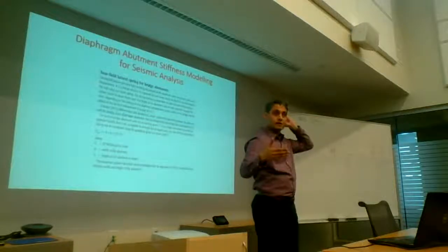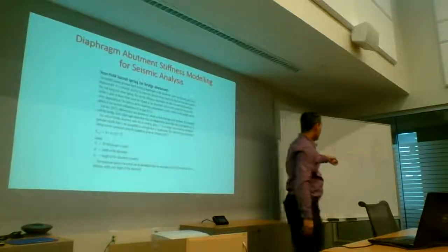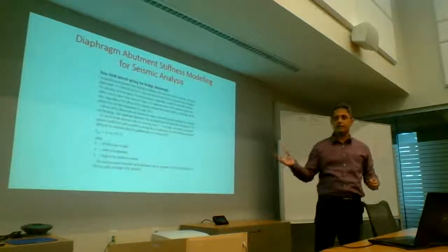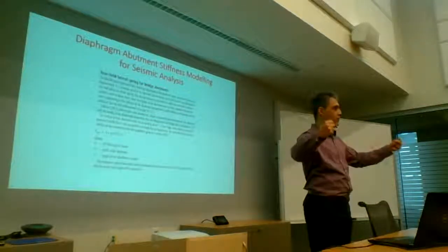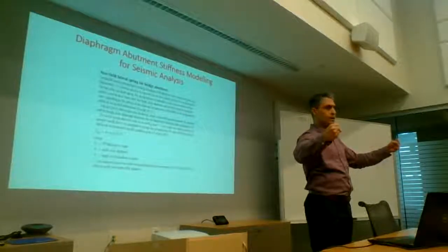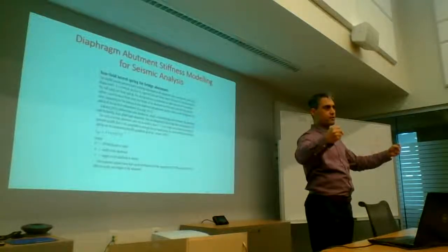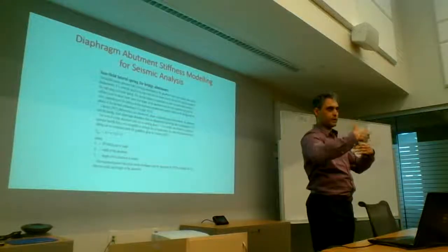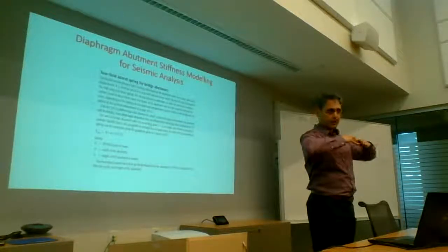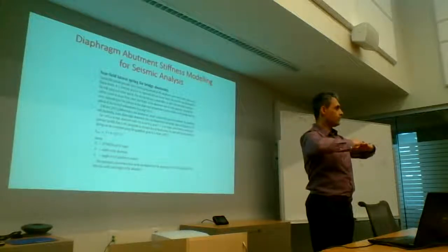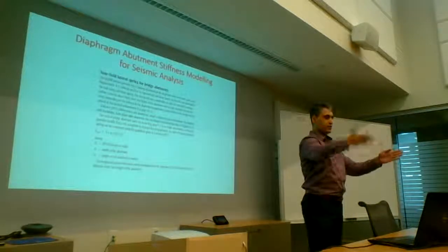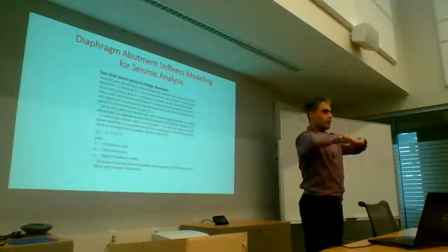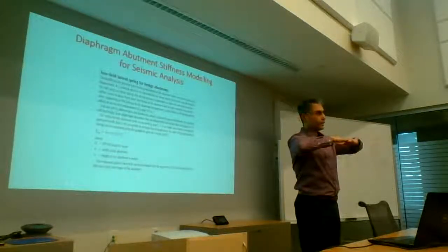We've done lots of retrofits where it's very tedious to go and retrofit the columns. There are a gazillion deficiencies with them. What we do is we go and retrofit the abutments and we make them very strong and stiff. And we do that in cases where the deck aspect ratio is helping us. And we make them work as a stiff diaphragm. You might have construction joints from span to span. We go in and we put link decks, so we put continuity into the deck.